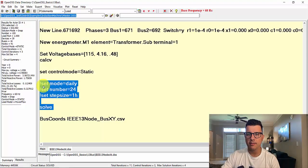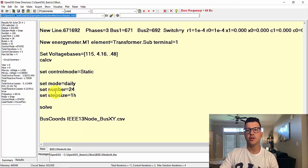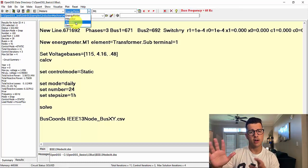So let me come back to my lines of code. One thing that we need to use to get results in a time series mode is to use our meters. So we have here different types of meters. The two that I'm gonna focus on in this video are energy meter and monitor. In more advanced tutorials we talk about the other ones, but here just the two of them.